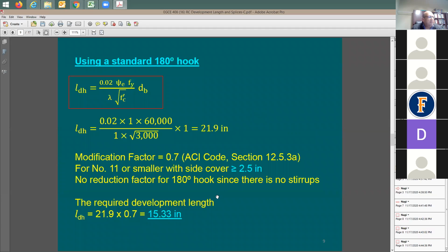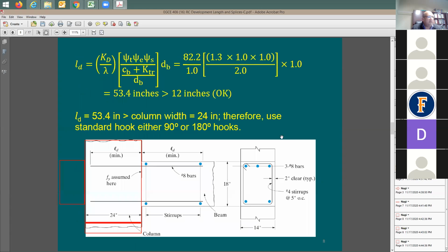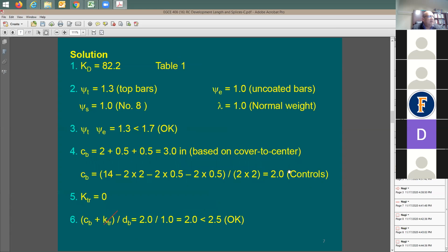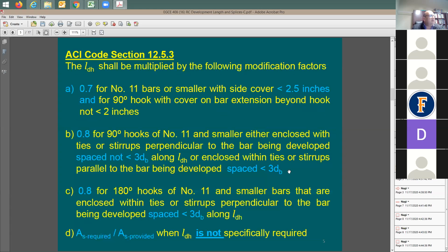And then, if we increase the epoxy coating, or the coating on the rebar, that would just increase our Ldh, right? Exactly. Yes, absolutely. Okay, thank you. So with that, I said, well, this looks like it's going to be a very good option, 21 inches versus 54 inches. So I said, you have more factors here that I just skipped. Now I need to go back to it and see what these factors are for.